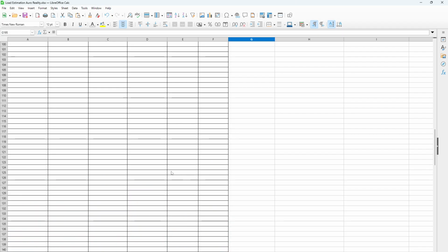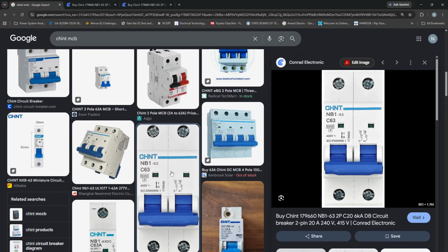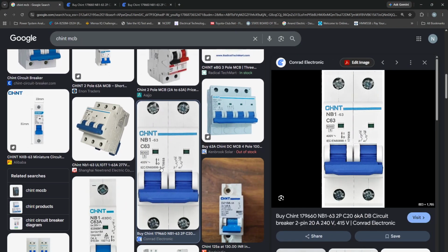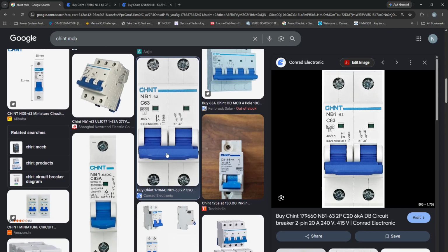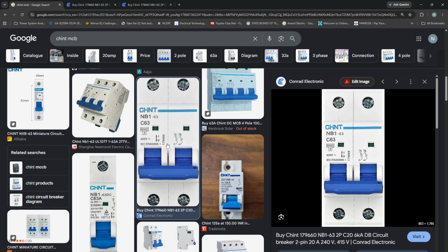So basically you take the rating of your transformer, and from that you calculate the impedance, and on that you get the short circuit currents. So if you go with your electrician, if you are on a budget, then there is no option. That is the only way. But if you can afford an engineering service, then you better go with an engineering service like this.